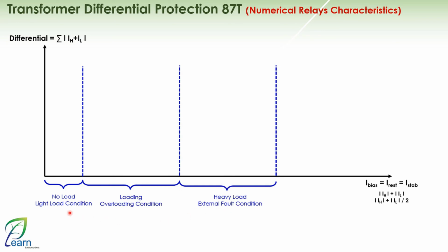Very nice. Okay. When we go back to the beginning, it means that there is one breaker closed on one side of the transformer and the other breaker is open. Therefore, you have a load on the transformer. There might be a load on the cable that goes to the transformer, and so on. All these currents are read from one side of the transformer, and the other side will not be reading any